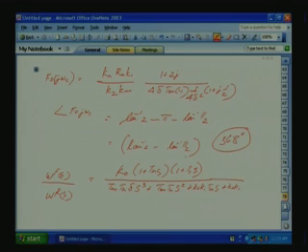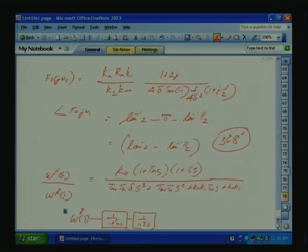The effect of the zero we know from the current loop how to cancel. When you have the speed reference, that is our omega R(s), you pass it through another filter, 1 by 1 plus Tn s, then again 1 by 1 plus T1 s, or you can combine these into one filter, then the feedback should come here.